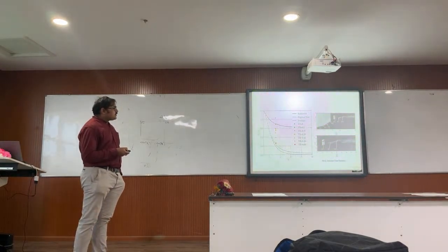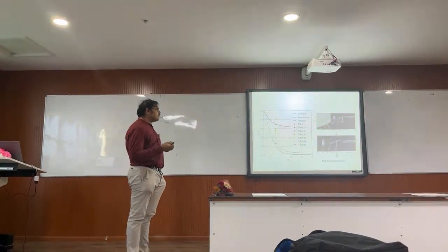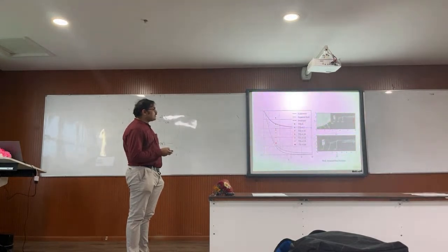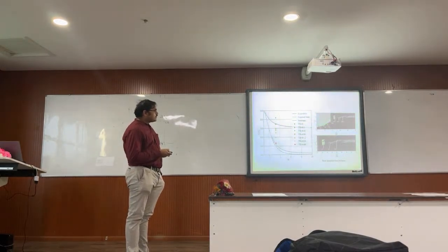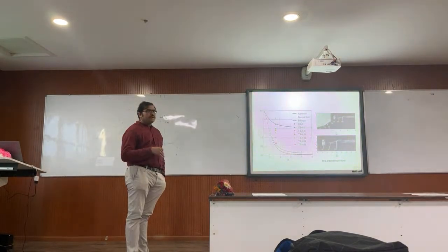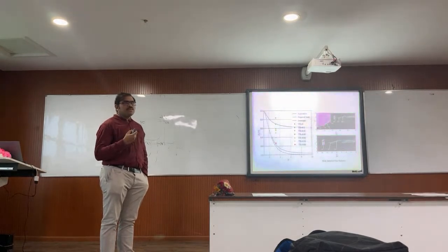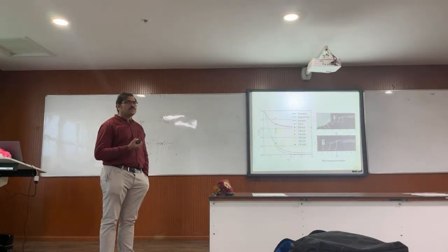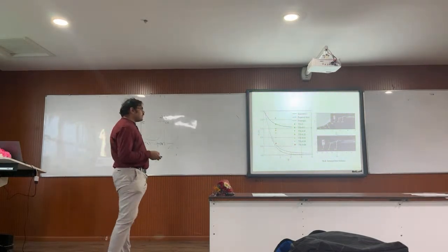While those with the yellow color markings, 0.35 and 0.42, showed that they were started when we moved the flap to this particular position. But if we fix the flap to a throttling ratio of 0.35 and 0.42, and then start the tunnel, then it goes into unstart. So if we have an initial started condition and try to push it to unstart, it remains started. But if we start off with an initial unstarted configuration, then it is unstarted. So it is in the dual solution domain.